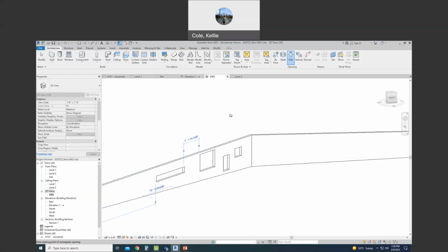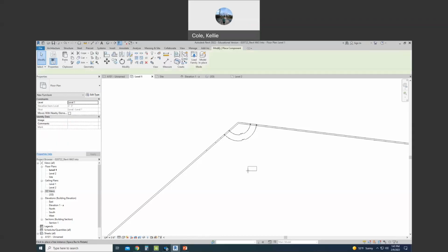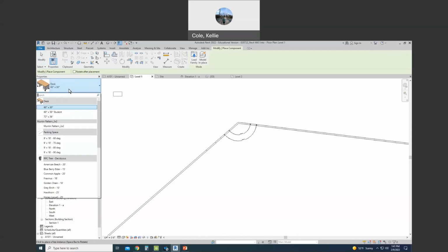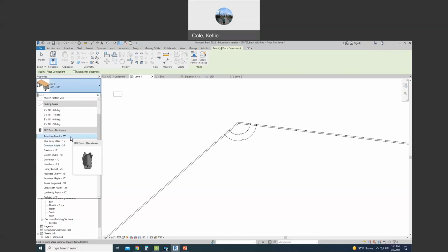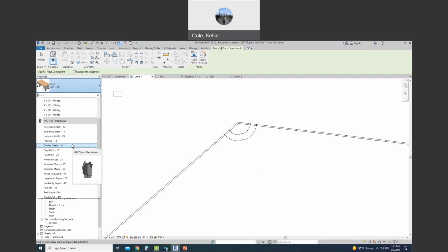And then to get out of the command, I can hit escape. But we can draw our own components by component modeling. All right, so I'm going to use CM. And when I type CM, all of a sudden you see that, oh, I have a desk that appears. If I click on the desk, I see that there's trees in my Revit, right? All kind of furniture-like or family-like things.